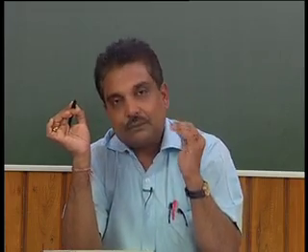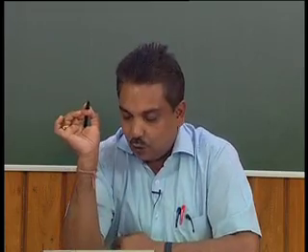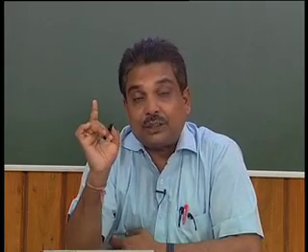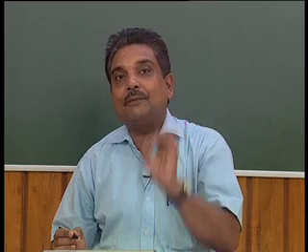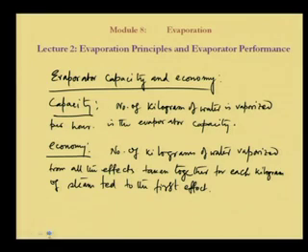When you have such effects together, the total amount of vapor vaporized for feeding 1 kilogram of steam is very important. However many effects you have in the system, whatever total amount comes out, it comes out for only 1 kilogram of steam, and that steam is fed into the first effect. This is the convention: the effect into which the external steam is fed is called the first effect.